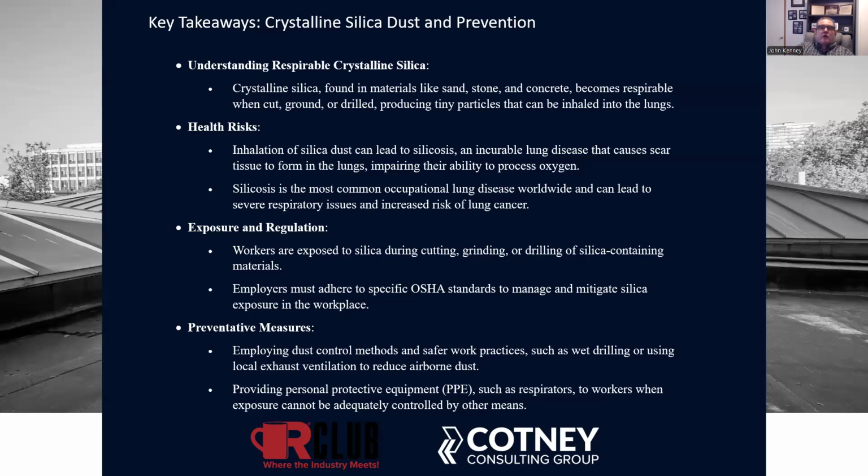So what are some of the key takeaways from this, right? First of all, you must understand what crystalline silica is. We've covered that. Health risks. We've talked about the health risks. It is a serious health risk if you are exposed to it. You don't want to expose your workers. You want to avoid this at all costs. Exposure and regulation. Workers are exposed to silica during cutting, grinding, drilling of silica-containing materials. Employers must adhere to specific OSHA standards and mitigate silica exposure in the workplace. So again, like all other aspects of OSHA, workers must know what they're exposed to, and you must prevent it and have training in place for that.